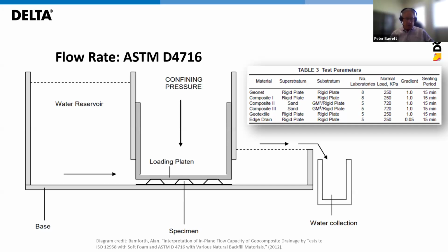But there's a bunch of considerations with this test, and there's choices that you can make in the performance. There are several different test conditions. One is slope. If you see somebody publishing a measurement on a 0.1 slope, then they have measured it horizontally. If they have measured it at a 1.0, then they have measured it vertically. There's also varying compressive pressures that one can put on. You can put in different substrates. You can put in different loading materials.